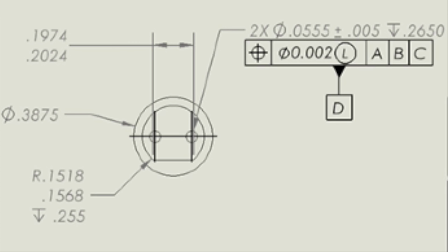From the front view of the male socket, we can establish a fourth datum, datum D, which has references to datums A, B, and C and lines up with one of the prongs that mates with the female connector and forms a connection that electricity can pass through. Since this dimension has to be precise, we chose a tight overall tolerance of 5 thousandths of an inch as well as a position relation and 2 thousandths of an inch of tolerance zone size.